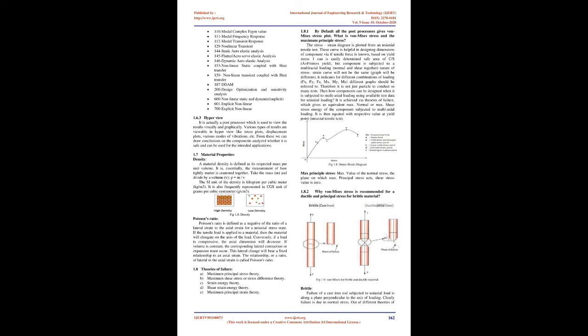1.5.2 Processing. Processing means solving the given problem, i.e., internally the software carries out matrix formation, inversions, multiplications, and gives the solution for unknowns, i.e., displacements, strains and stress for static analysis.